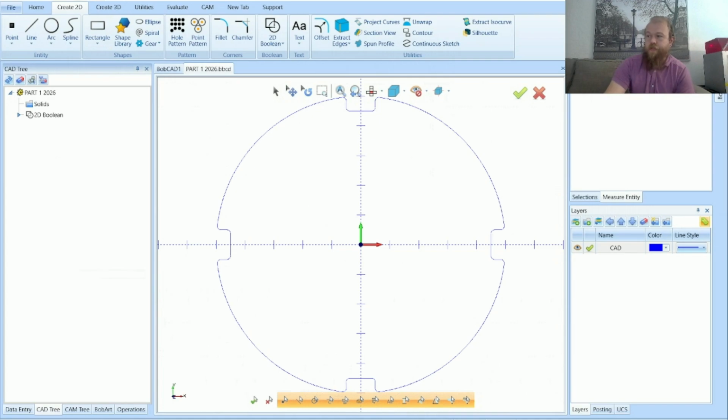All right, so far we've made a 10-inch circle for the OD. We made 1-inch squares along the sides here, every 90 degrees. We made the 2D Boolean subtract, and we made 1/8 inch fillets for every corner on the drawing. Let me know if you guys have any questions in the comment section. I'm going to add the next step there in the comment section.